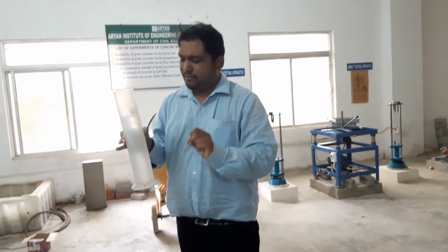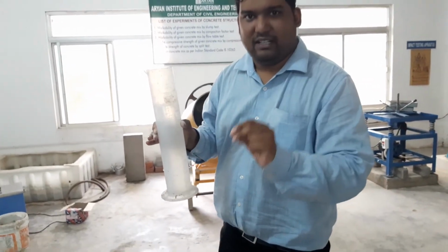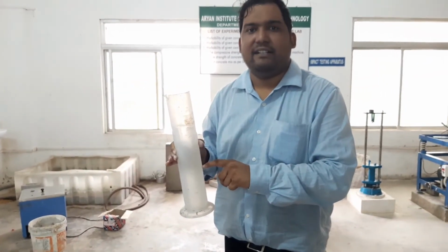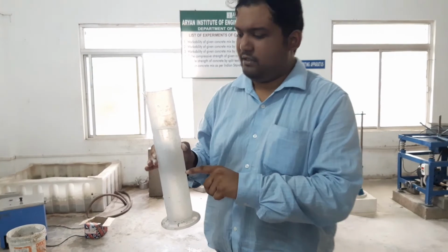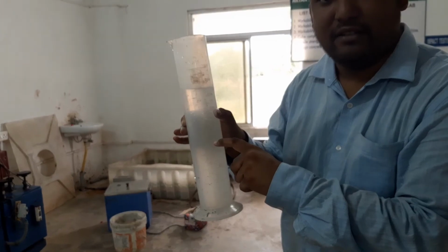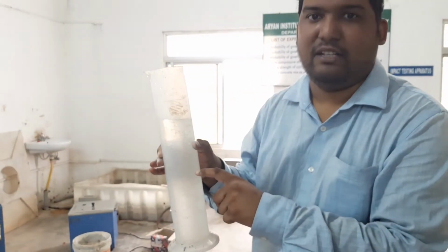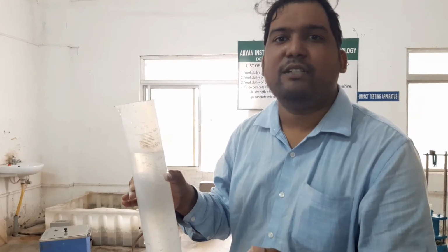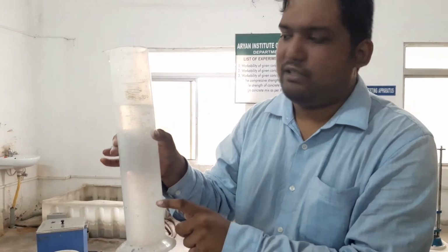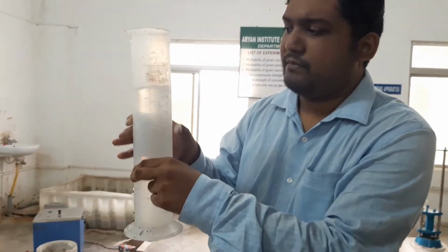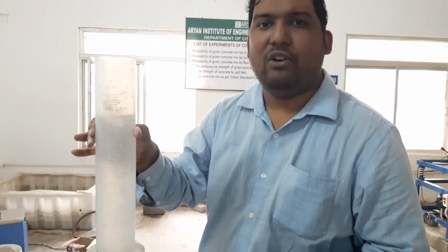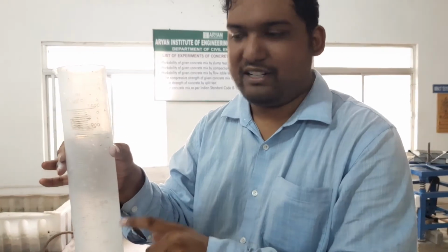Means if I have taken 1 kg of cement, in that 1 kg I can mix maximum 500 gram of water. Okay, we should not be confused that water is measured in liter. Then how can we find what should be the amount in gram? So this is a measuring flask. First we can put it into a weighing balance to know its mass. Suppose this flask is 200 gram.